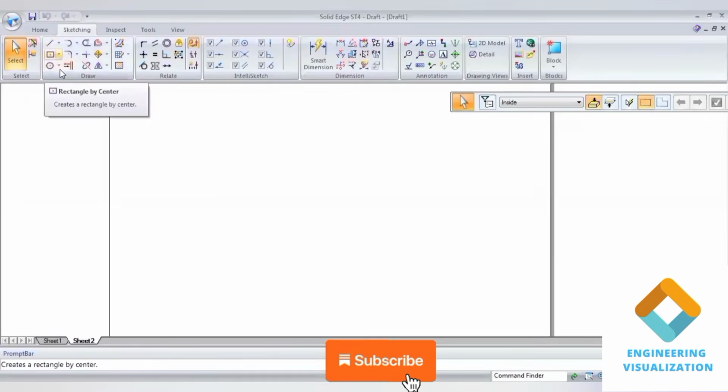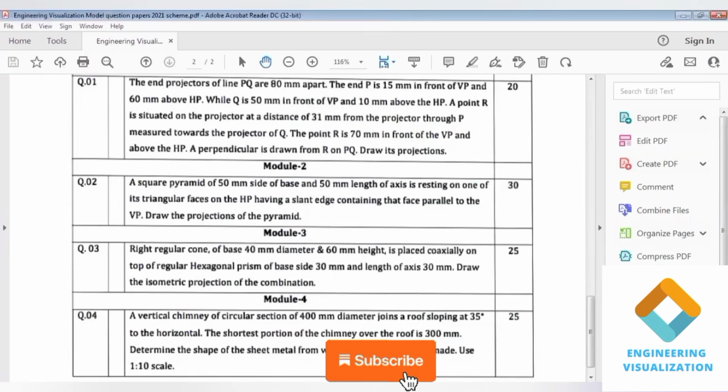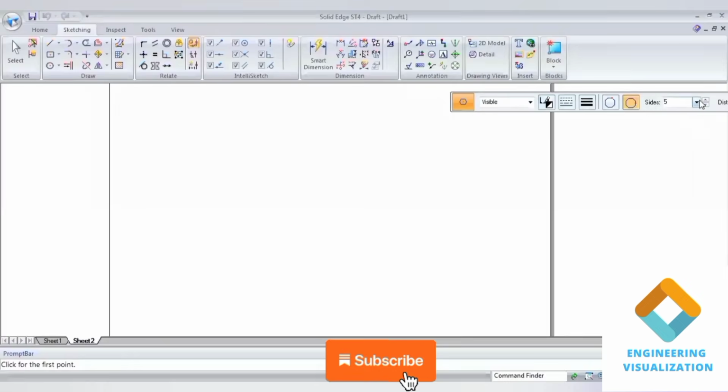That means first I should construct this hexagon. That is, first I have to draw the orthographic top view. So remember, for polygons such as triangle, pentagon and hexagon, we should always construct the orthographic top view because you require box dimensions in order to construct it.